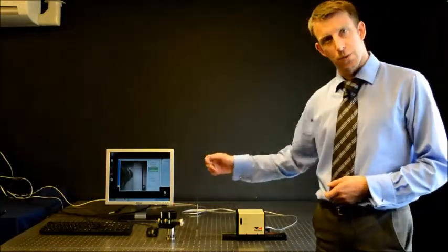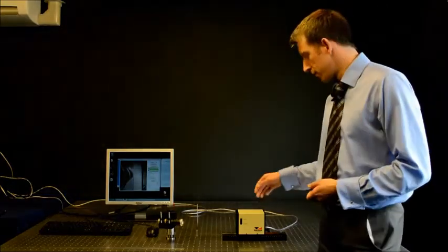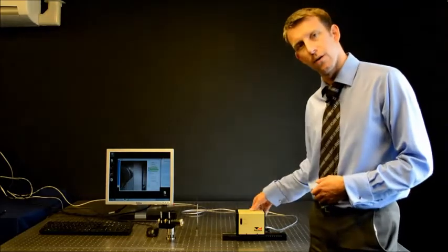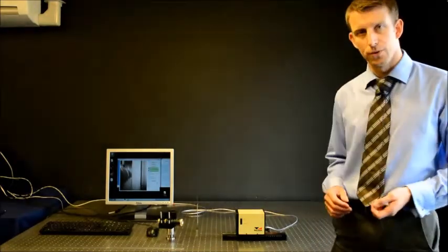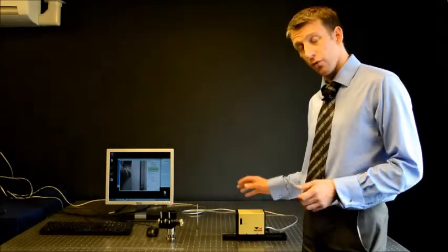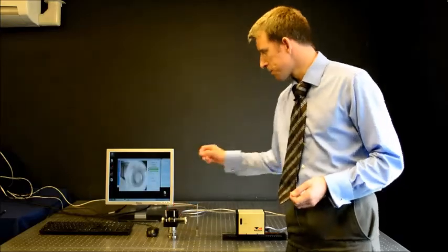When a light source is switched on, a lot of light will reach the CMOS camera. And for this reason, to the rear, from this view of the PSL Profiler, is provided an ND filter wheel. This filter wheel has in position 1 no filter, so one can see the source under test.